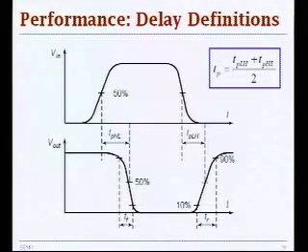So how many gates are around? How many gates do you have at the output of your gate that you need to drive? How much parasitic capacitance do you need to drive? What is driving your gate on the input side? And that defines the shape of your voltage waveforms.